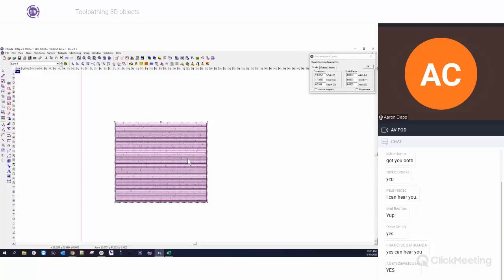For example, you have to select the relief before you apply the toolpath. Many times, if you're dealing with multiple reliefs, or if you have to select several different things with masks, and we'll talk about masks in a little bit, the software doesn't remember that those are the last things you had selected when you applied this toolpath. And when you edit it and then hit OK, it'll sometimes mess up that toolpath.